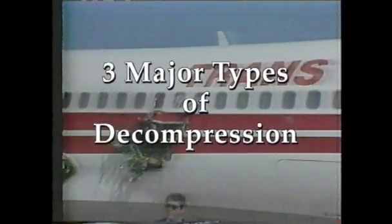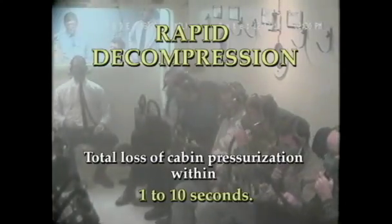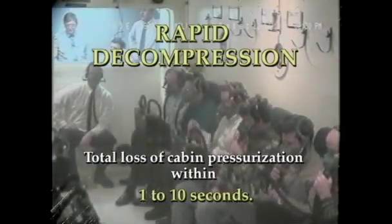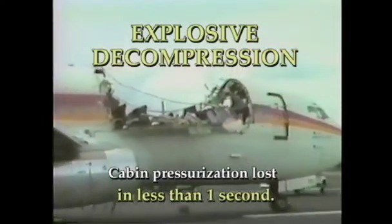The 3 types of decompression are slow decompression, where cabin pressurization is lost in 10 seconds or more. Rapid decompression, where the loss of cabin pressurization happens within 1 to 10 seconds. Explosive decompression. Cabin pressurization is lost in less than 1 second.